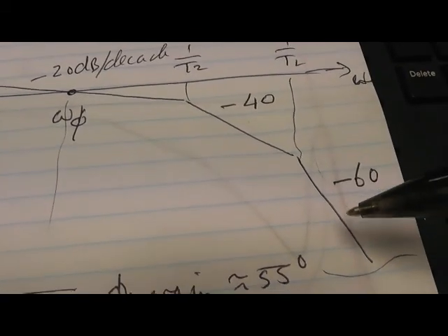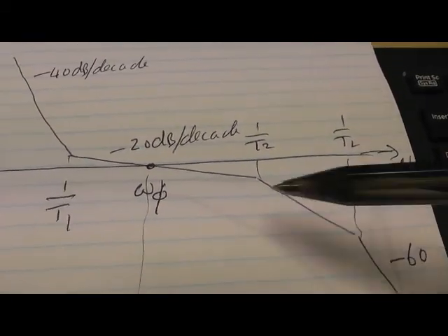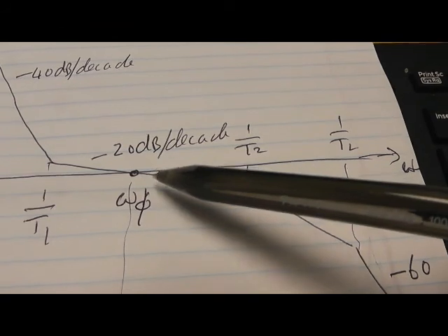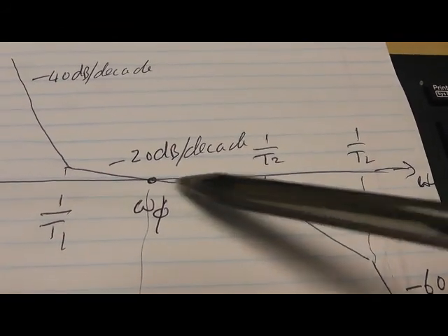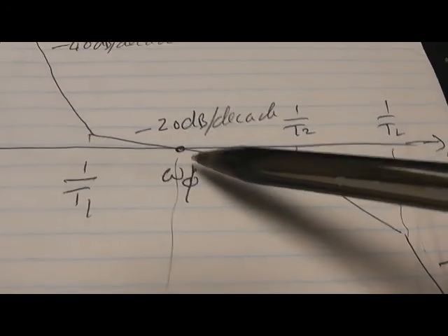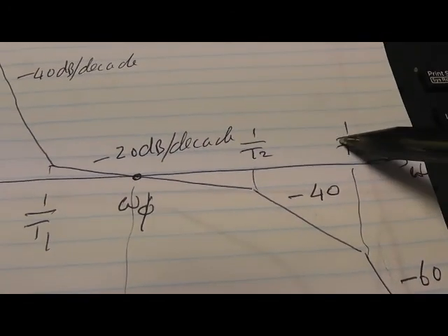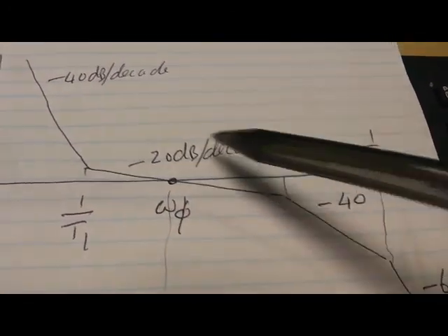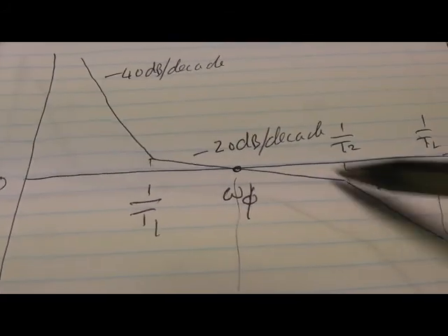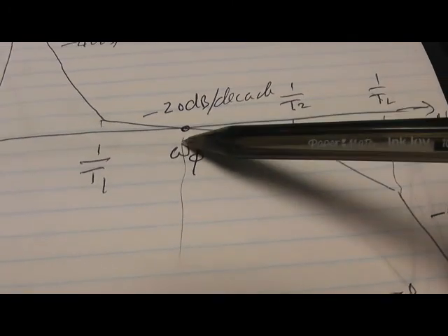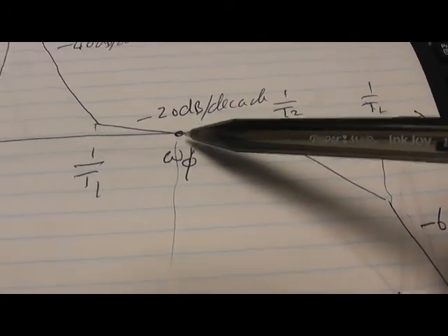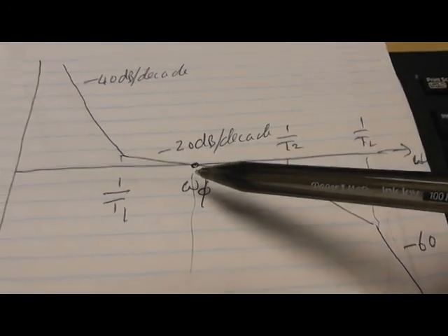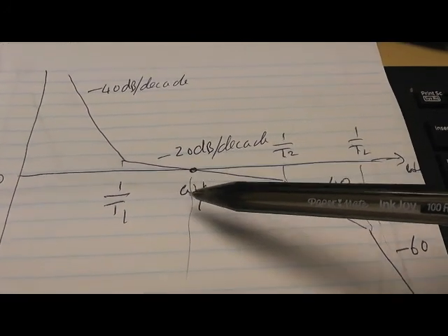And then the roll off at high frequencies, that's okay. There's a little bit of attenuation here. And provided the bandwidth here is satisfactory, we can get away with that. The ratio between this one and this one is again what we call the span ratio. It spans unity gain, and this is our bandwidth, and that defines the speed of response, how fast the thing's going to go, the rise time in other words.